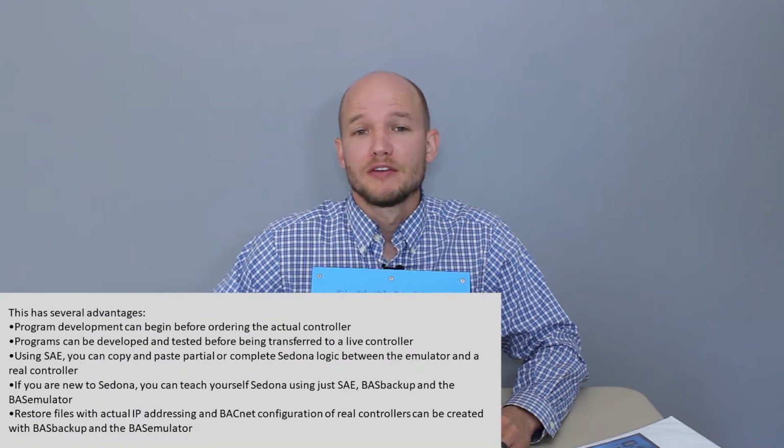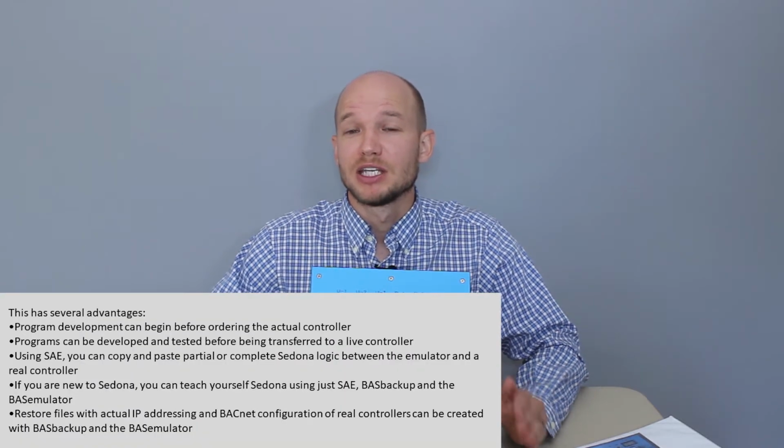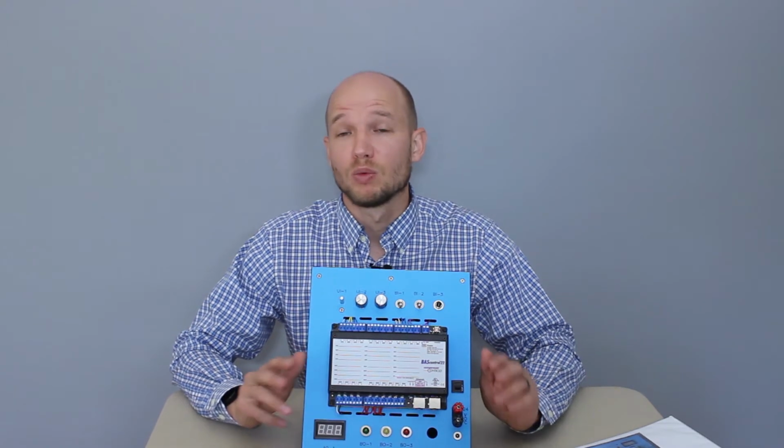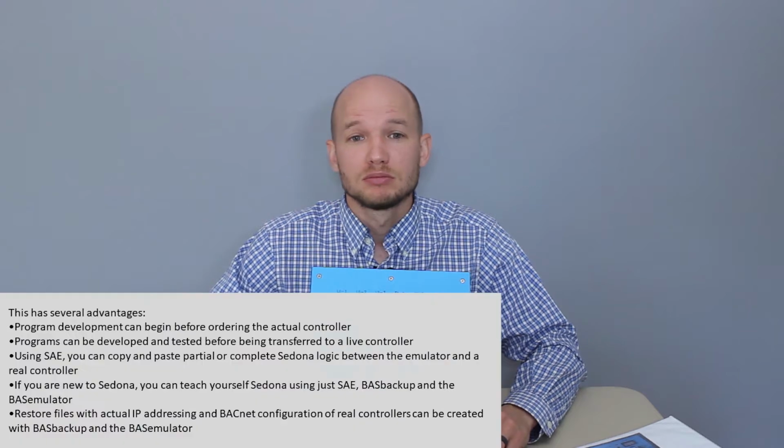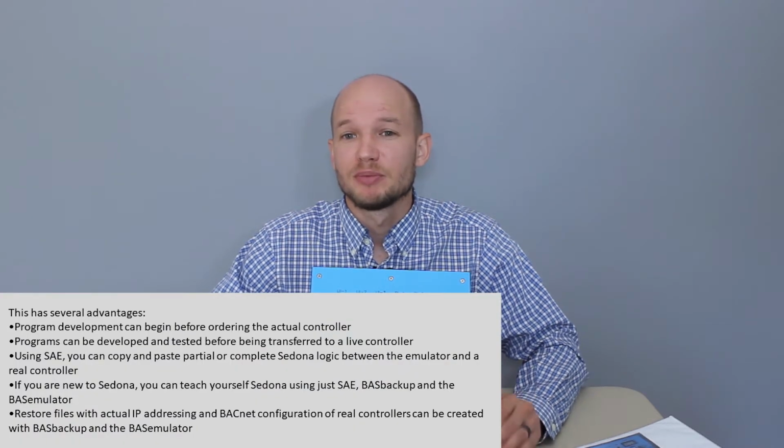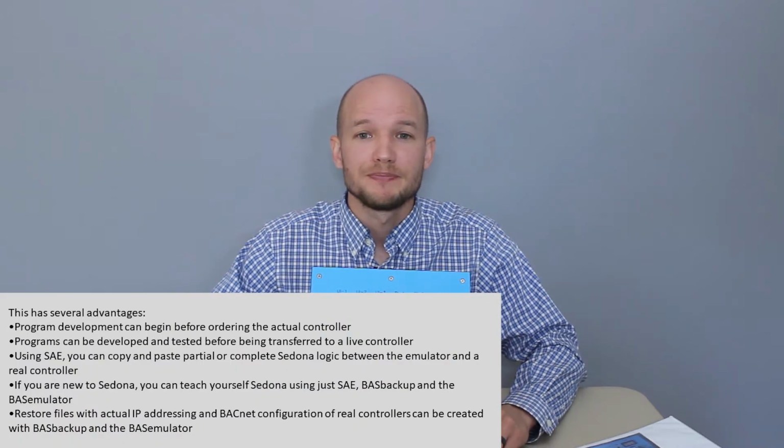So emulation has a lot of advantages. There's a couple listed out here. The first one being program development can begin before ordering the actual controller. This is huge. If your company is on a tight deadline for a building or facility or a complex, you can start the programming days or weeks in advance, and when the actual controller gets on site, you can just transfer your programming over. The second one, programs can be developed and tested before being transferred to a live controller.